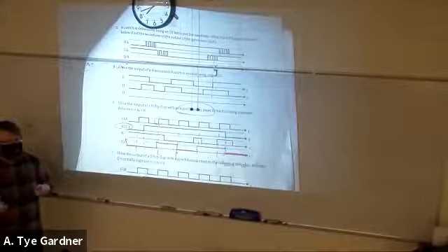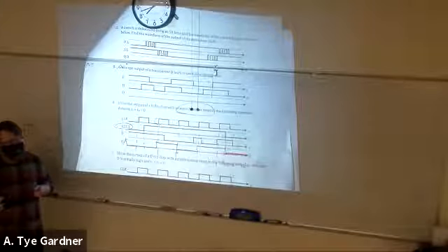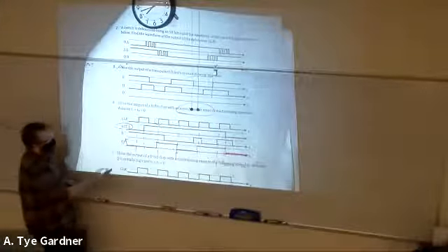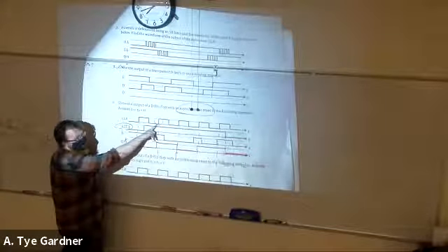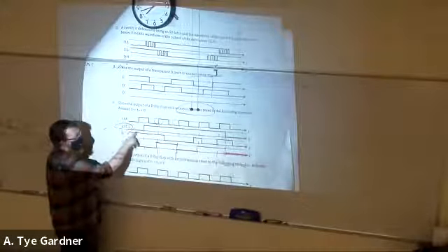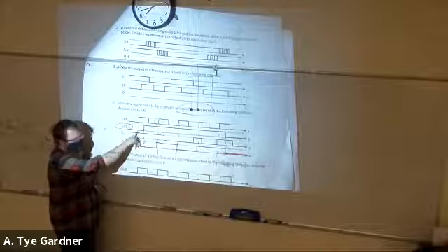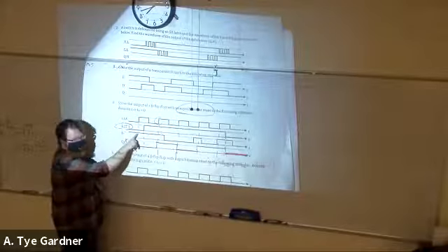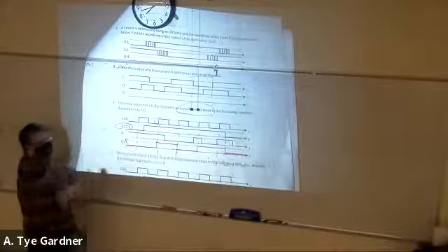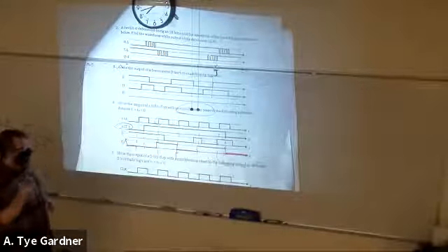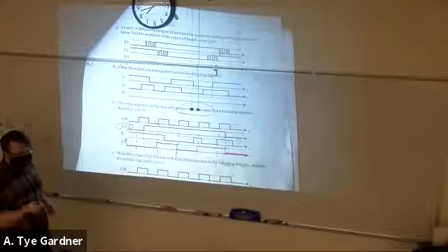So it's like it's 0, but then even if it is 1, it has to be updated still. Yes, exactly. The first update is this rising edge of clock, because at this update, reset is true. So it doesn't matter that data is 1, because of our code that says if reset is 0, D is 0.